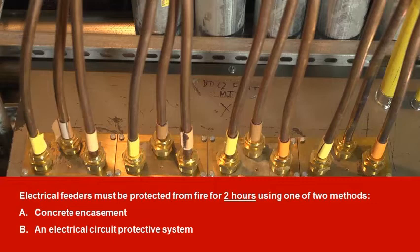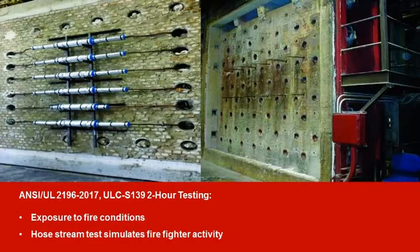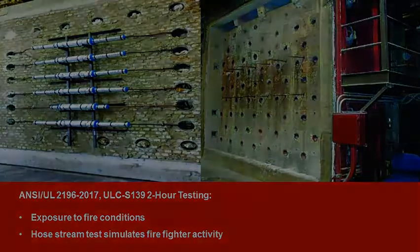A, the cable or raceway is encased in a minimum of 50 millimeters, 2 inches of concrete, or B, the cable or raceway is a listed electrical circuit protective system. Informational note number 1, fire-resistant cables are tested to ANSI UL 2196-2017, ULC S139. Let's take a look at each method.